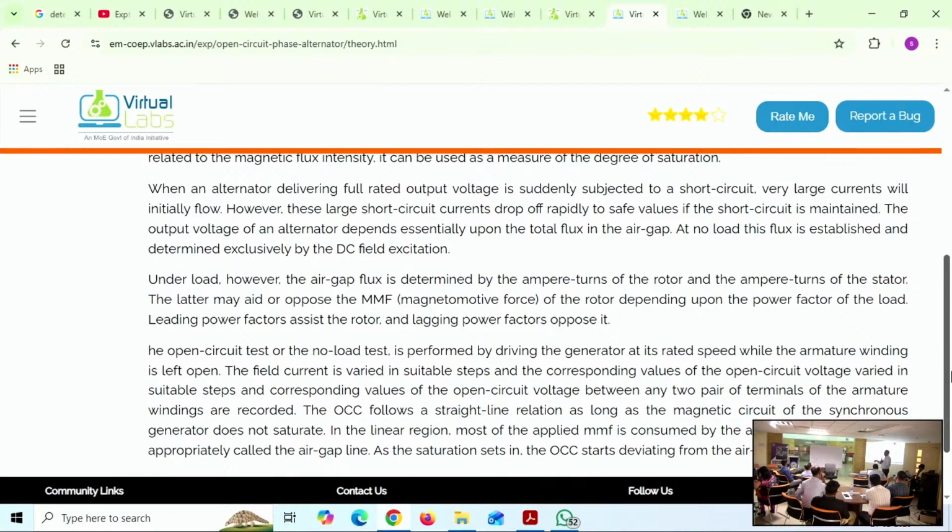Say in our solar installation systems, we have arresters, an inverter, a battery, and our household appliances. If protection is given at each and every stage, that is more protective. If they connect one arrester and one grounding and leave it, there may be no problem, but a problem may arise and cause severity. So the minimum protection must be assured. The experimental setup should first run in the mind.